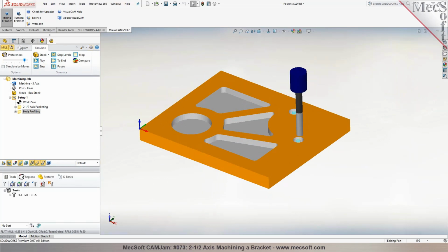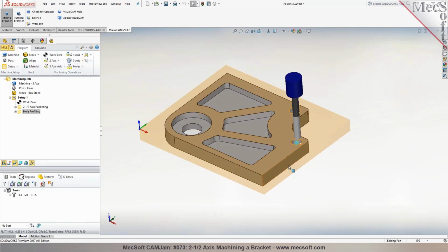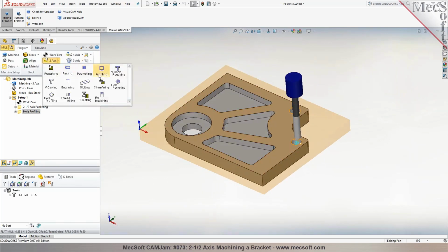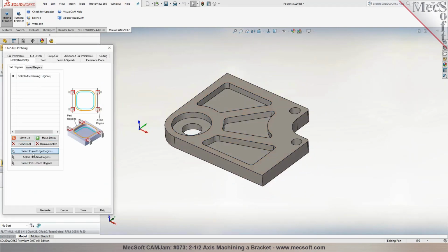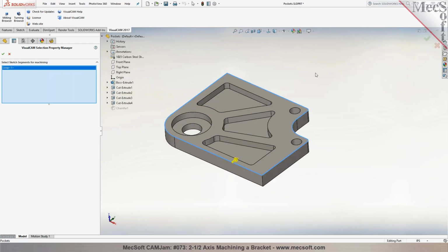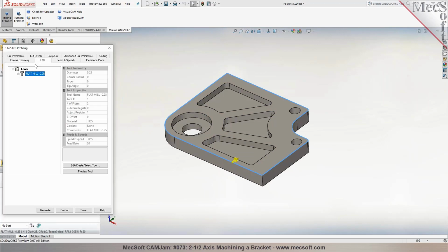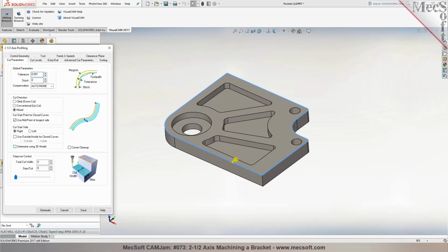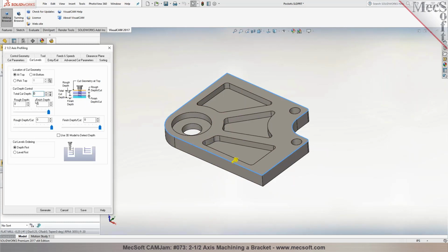And finally, you want to do a profile cut to relieve the material. You go to 2-axis, select Profiling, and I can right-click on this and pick Select Loop. It picks the entire loop around the part. Specify the properties. You can choose to determine side to cut based off the 3D model. Use the midpoint of the longest side for the location of entry and exit.